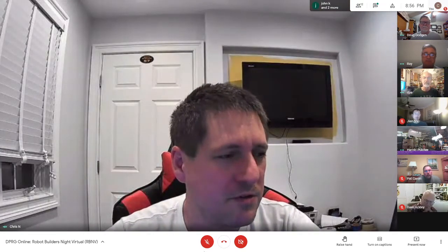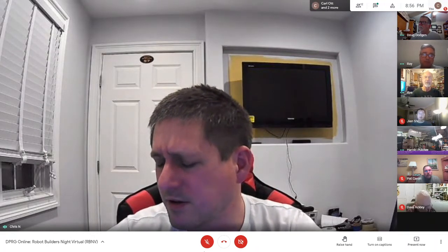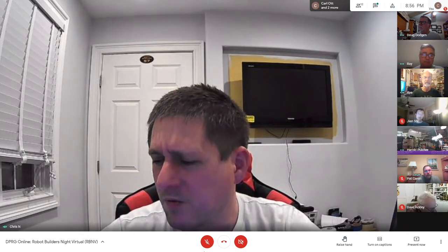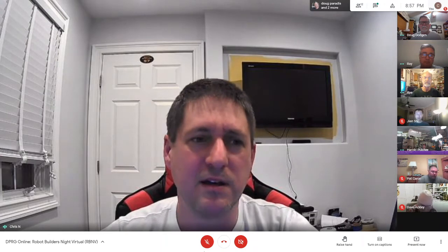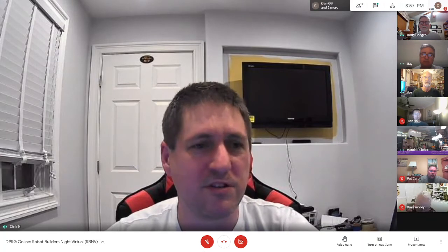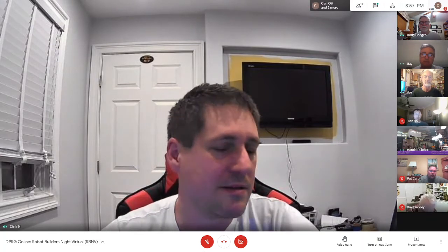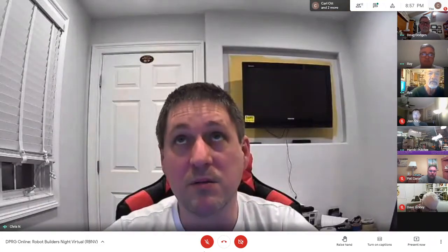Yeah, I think you bring up a valid question. With some of the hacks that I've done previously, and I don't know if you were in some of those calls, Dave, I get the sense that if it's within 100, 150 milliseconds, you can drive a robot around at moderate speed, right? It's all a function of speed ultimately. The more the lag, the slower you gotta go, right? So we're talking about an update rate on the order of 12 hertz? Not update rate. We're talking more about the lag, right?